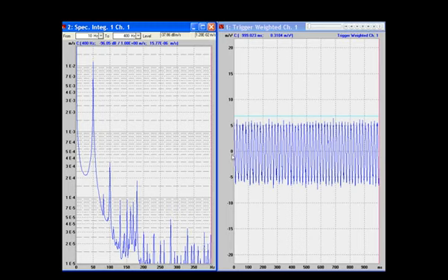Now, one problem with this, and it occurs on all FFT analyzers, it doesn't matter whose, you get something called a truncation error. We've opened our eyes, we've opened a switch, we've allowed data in, we've closed our eyes, we've closed the switch, we've stopped taking data, and that creates a step function at either end of our signal. And the frequency analysis of that step function gives us lots of sidebands on our spectrum, and those sidebands aren't actually there. It's called the truncation error.